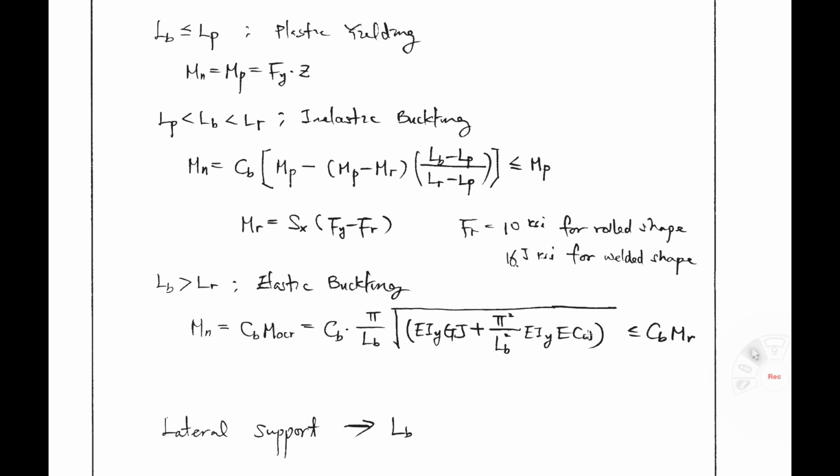So far we have covered elastic buckling cases, right? These equations, with different boundary conditions and different loading cases. Then how about inelastic buckling cases? In order to get values in inelastic buckling cases, we have to use numerical integration with a computer. So the LRFD standard provides these practical design equations.